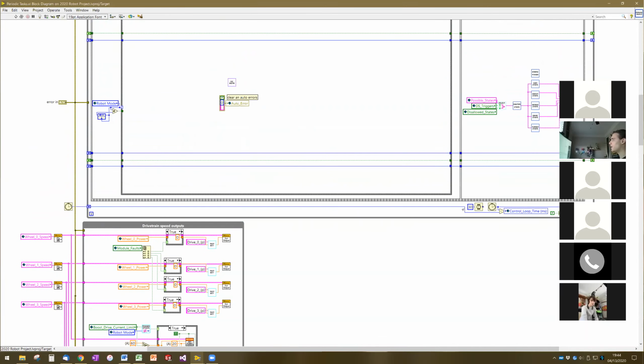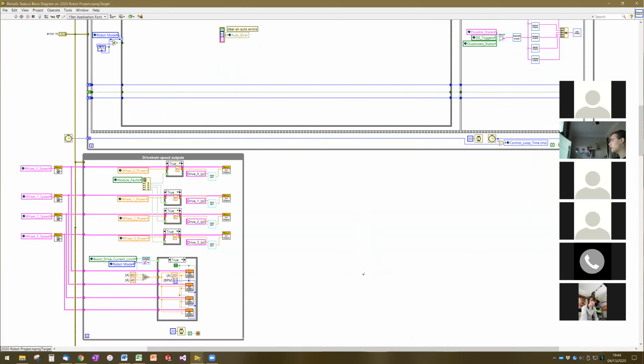And so if you're trying to maintain your control loop time at 30 milliseconds, and you need to update 4 motors, depending on how you do that, that might take hundreds of milliseconds. And so you could basically lock up your robot for the entire time that you're trying to send those update commands and prevent you from doing anything else.